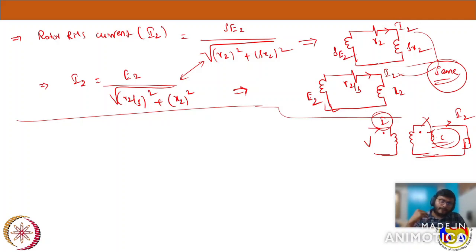Now I have connected a load here, and my secondary has drawn extra current. Now from where is the extra current coming, because my flux in the core will always have to remain constant? So when the flux in the core is always fixed, and I am asking the secondary to draw extra current I2, from where should that current come?